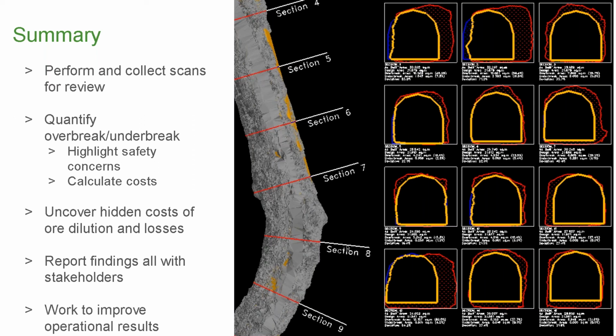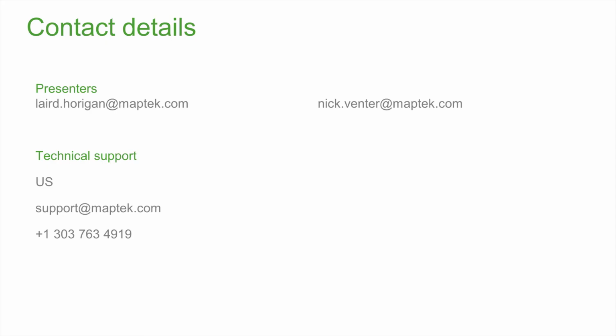You'll see the image to the right here is generated with a sectional-based system or analysis with the distance along center line to determine when the sections should be calculated. Here, with just the 3 inputs of the center line, the as-built, and the design, we're able to generate quite a bit of information and present it in a very logical or meaningful way. Similarly with the blue for underbreak and the red for overbreak, and a deviation percentage on each section, this information can be quite impactful.